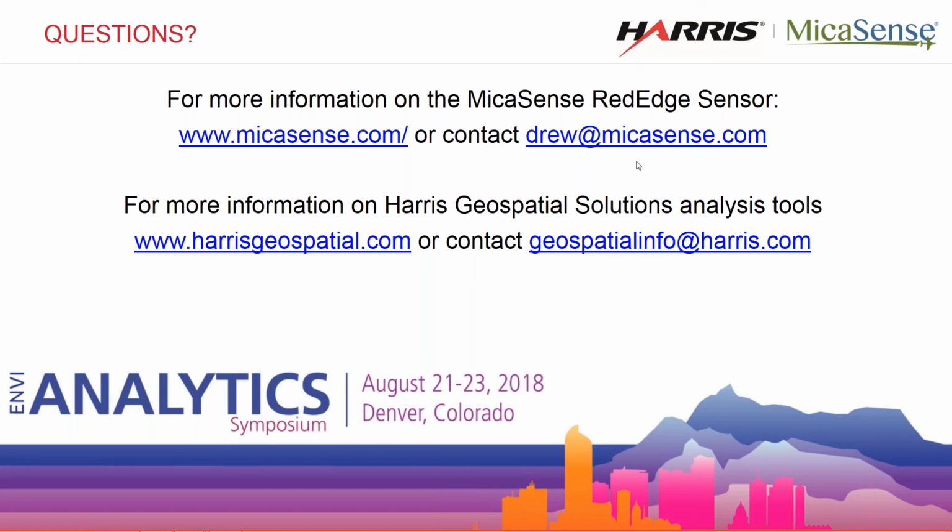Yeah, it gets pretty difficult. I know we had some people in Florida who were dealing with that same thing, and I've done some data collection in Iowa where it was similar, where you've got these puffy clouds floating everywhere, and you're just basically trying to find a moment in time where the field is not covered, and then you try to get your 30 or 40 minute mission in that time period. But it's tough. If the shadows are really extreme, it's really hard to remove those. The downwelling light sensors help, but they're definitely not a 100% solution yet.